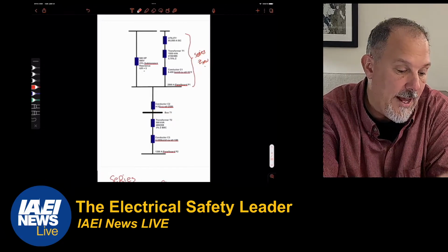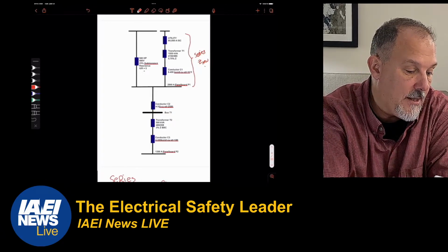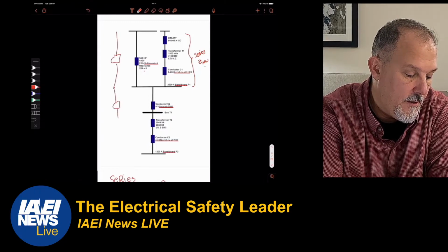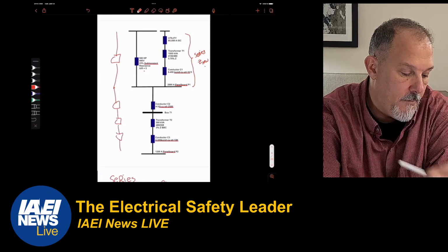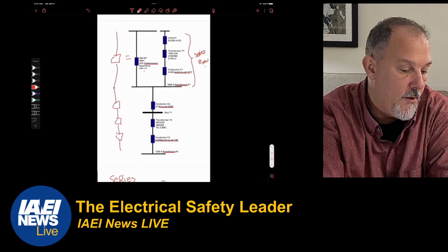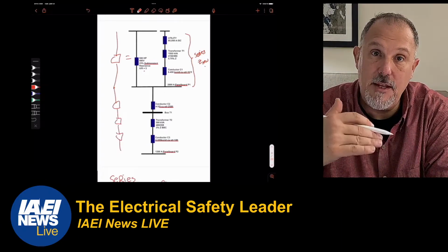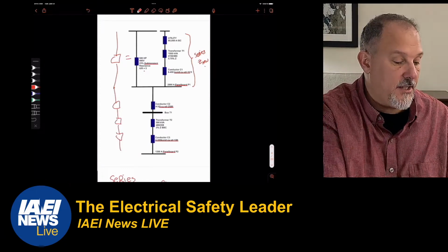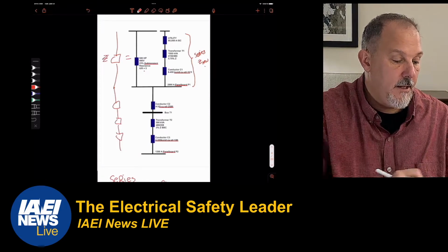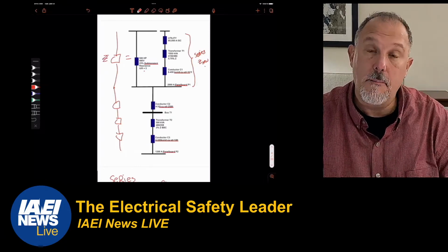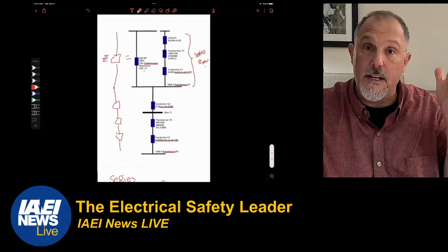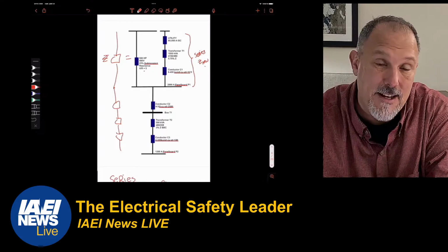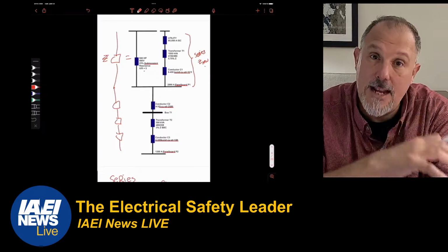to get what that circuit is, to get this to a single impedance. So I need to add things in series first, combine them in parallel. That becomes the Z new here. And then I just add those impedances in series and I get my total impedance, and then I calculate fault current from that. And I'll show you how that's done. But that's standard network reduction.